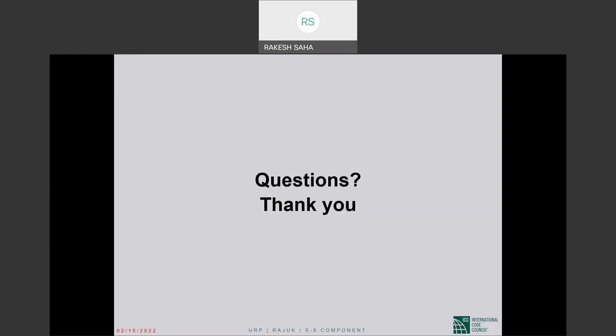So the next question is, in between modal analysis and time history analysis, which will give much better or accurate results? Which analysis do you suggest? I actually said this: elastic time history analysis does not give you any more information than modal response spectrum analysis, as far as I'm concerned. You may get more numbers, but no new knowledge of significance.